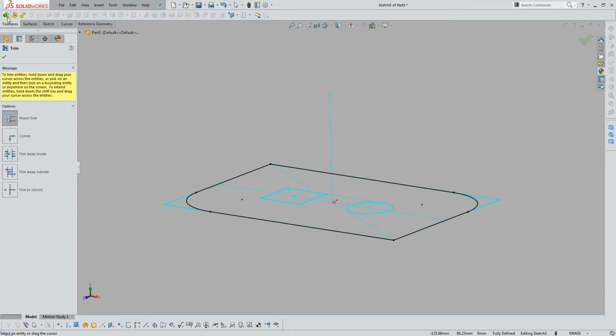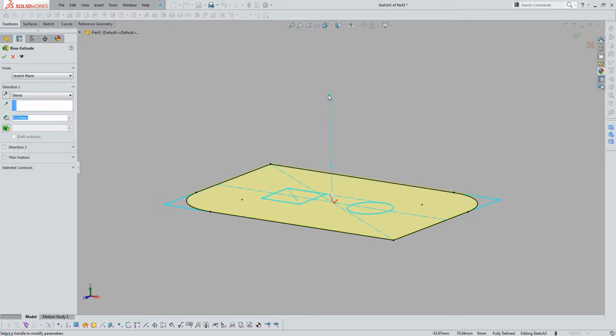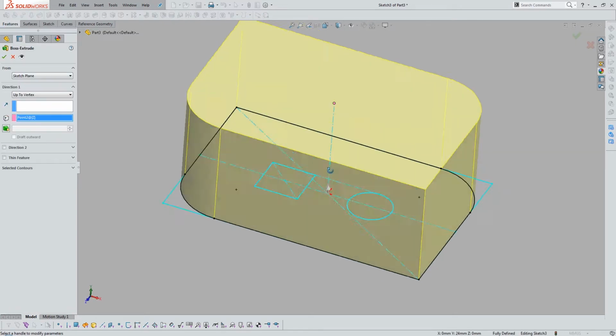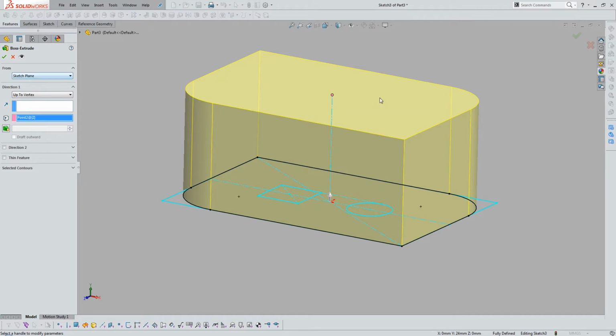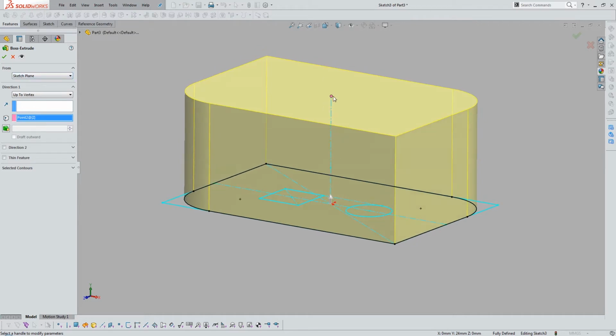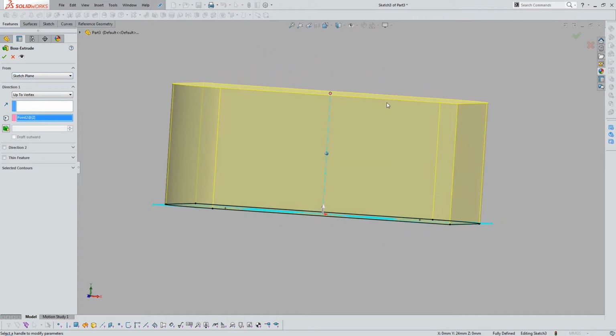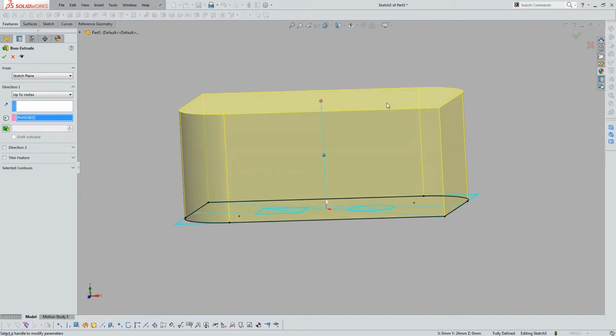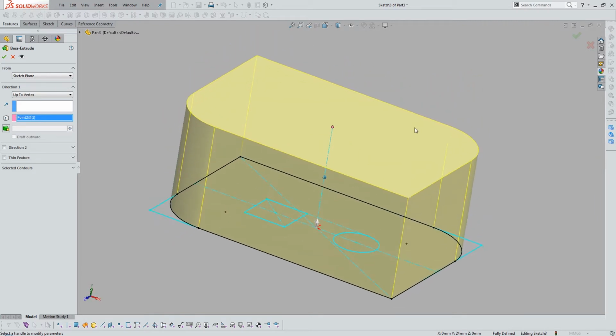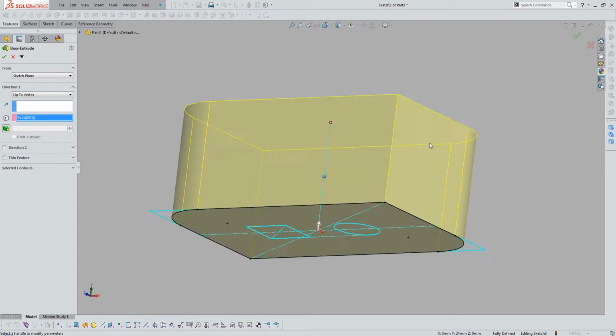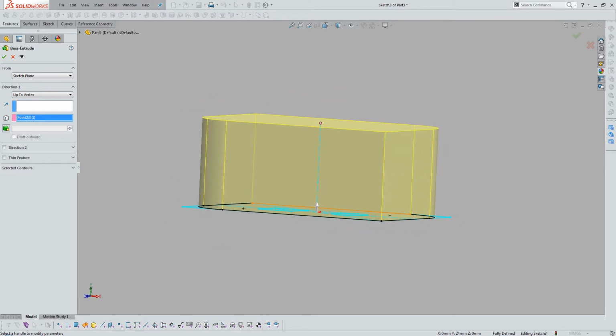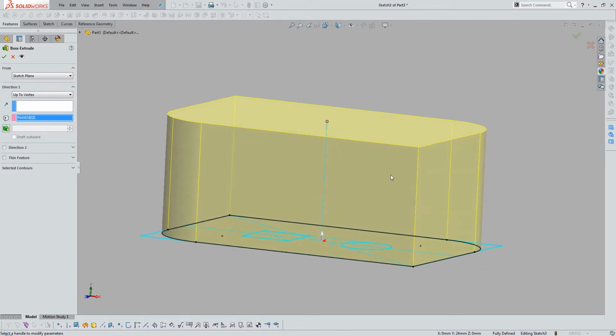And what we would have done up until this point is to create an extruded feature, like so. I've used, as you can see, this height reference in my front master sketch to tell me how tall to make that part. But instead, because I want to be able to pull this down out of a mold, I'm going to turn on my draft feature. So that's method number one, is to create extruded bodies with draft angles built in.